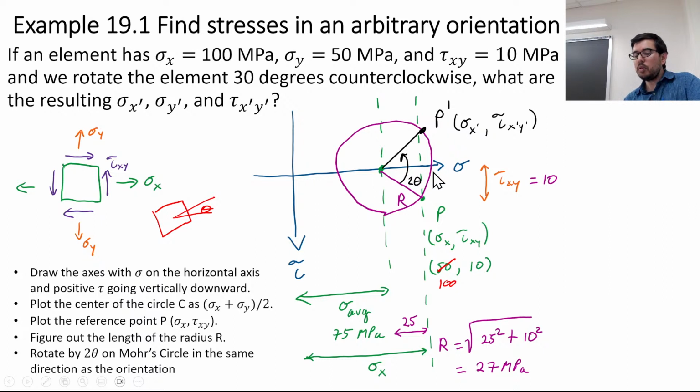The beautiful thing about Mohr's circle is that it clearly indicates where the principal stresses are and where the maximum in-plane shear stresses are. That is the beauty of Mohr's circle. So you guys tell me, if you look at this, first, I'm looking for a maximum in-plane shear stress. Where on this circle is the maximum in-plane shear stress? Where is tau max? Top and bottom, right? That's the top and bottom. So instantly, we know what that value is, okay?